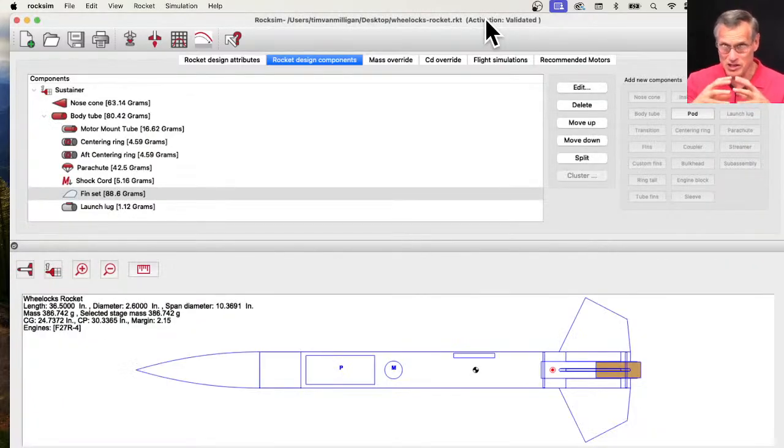So for example, one of the assumptions is the rocket has to be long. So if you try to make a short rocket, the Barrowman equations are going to break down. The other thing is the Barrowman equations only allow for fins that are either trapezoidal shaped or elliptical shaped. Now this is neither a trapezoid nor an ellipse. So the Barrowman equations could not do that shape, but RockSim can. We figured out a way to figure out how those affect the center of pressure.